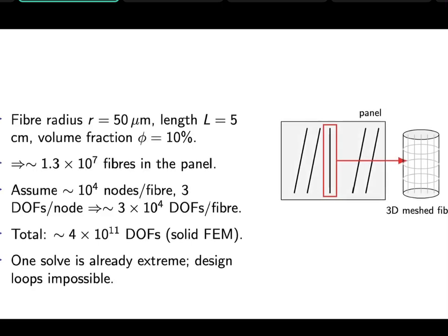So what is the next way that you can simulate? Remember, we're talking about a piece of wood that has fibers. These fibers can be modeled with a cylinder, and you can decide to mesh the 3D cylinder and allow it to deform in plane, so that section area could decrease. It can be elongated in the longitudinal direction. You can do all sorts of things that you are interested in.